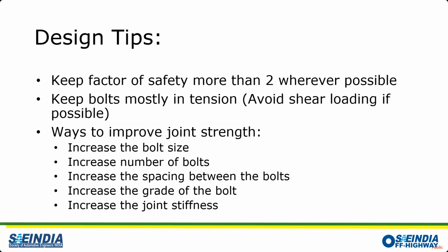Then you need to keep the bolts in tension most of the time. Avoid using the bolts in shear. That will keep your joint strong, and less chances of slippage.